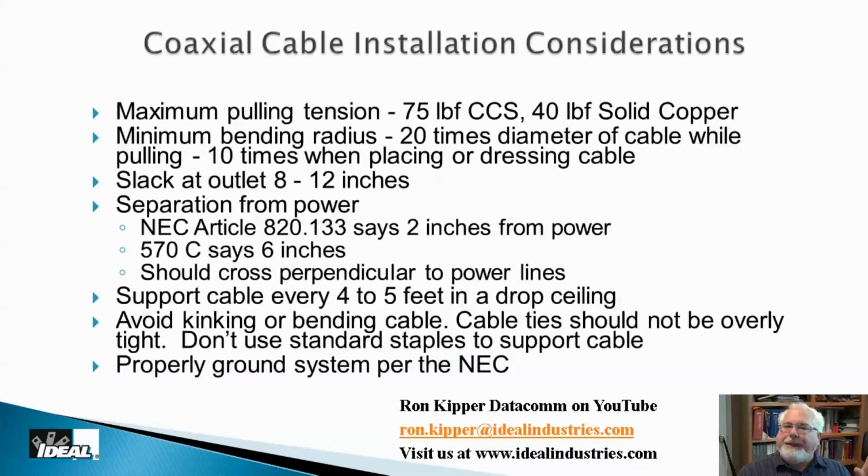Now, a couple basic tips when you're pulling the cable and you're getting it into place. The standards recommend that copper-clad steel not be pulled any harder than 75 pounds of force.